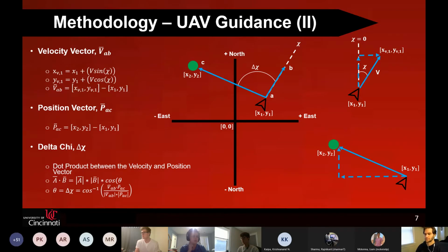What our waypoint system does is it creates 3 given waypoints. Basically, you have 3 set waypoints, and it continuously updates as the ship moves forward. When the ship moves forward, you have your first waypoint, which is substantially far away from the ship, then you have your second one closer, and then your third one is on the ship. This allows the UAV to get in a position behind the aircraft carrier and then straighten out so it smoothly lands onto the aircraft carrier.